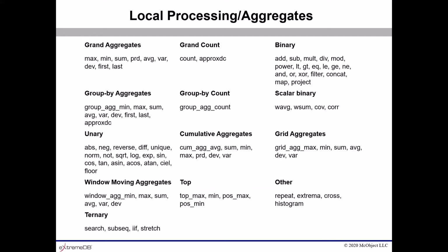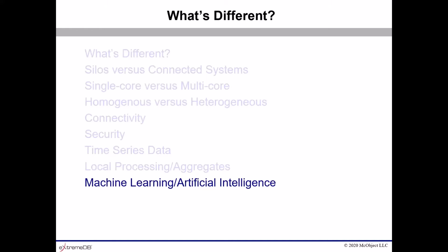Examples of machine learning at the edge are harder to find. But consider an adaptive transmission as one example. An adaptive transmission is one that learns your driving patterns and modifies the transmission's performance accordingly. In other words, the adaptive transmission might delay shifting if it senses high lateral acceleration, or provide for snappy shifting for an aggressive driver, or softer shifting for a more laid-back driver.